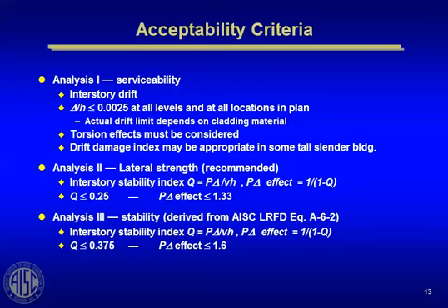And then we do everything we can to accurately model the frame. That is, we consider the composite stiffness where it exists. We consider the foundation boundary conditions to do as good a job as we can in predicting the drift under the service load combination that you're assuming. That includes, and this is one man's opinion, that you need to consider the P-delta effect in the drift calculation.